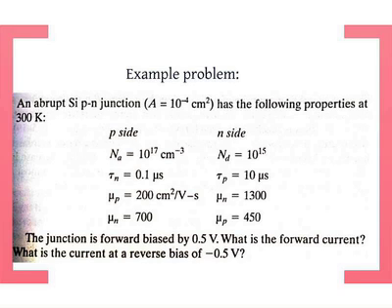Okay. Pn is the minority carrier concentration on the n-type, the hole concentration on the n-type material. You should be familiar with this, but you can use the expression that n times p is Ni squared. Okay, this is the equilibrium concentration, right? Even though the whole system is not under equilibrium, these things are equilibrium concentrations. Why? Because we have already taken that e raised to minus x over Lp into account already, so it's already there. Okay. So this stuff you can calculate. The Ni squared you know because the temperature is given.